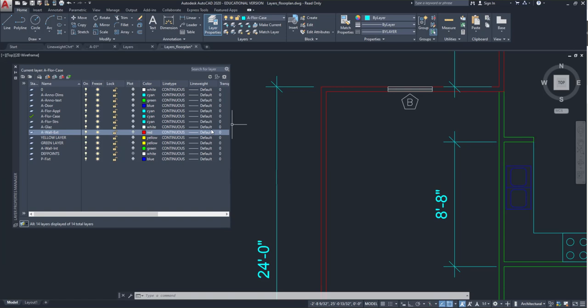The idea behind a pen file is that you could assign red to a layer in this file, and somebody could give you their pen file, and that pen file would define what red means, okay? It's confusing if you haven't done it before, but within the same office. So for example, I worked at a firm where we did work for National Park Service, okay? We did things as an office one way. National Park Service liked things done a completely different way, all right?